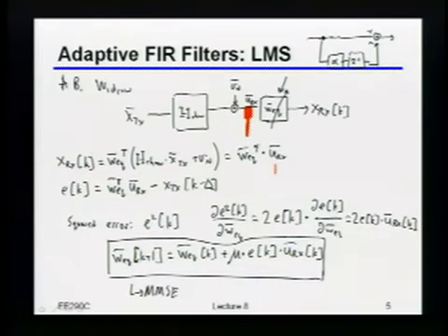Maybe just to say it another way, when I look at this one-tap example, the vector that I would be working with would really only have one entry, because there's only one free coefficient that I'm tuning. So I would update that coefficient by whatever that mu step size is, times the current error, times that vector, because I'm only able to tune that one coefficient. That's why I have to move this back by one, because I'm doing the single post cursor.